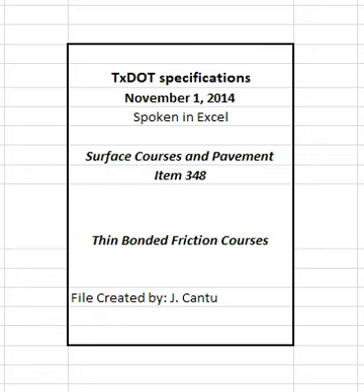Referee tests will be performed only on the sublot in question and only for the particular tests in question. Allow 10 working days from the time the referee laboratory receives the samples for test results to be reported. The department may require the contractor to reimburse the department for referee tests if more than 3 referee tests per project are required and the engineer's test results are closer to the referee test results than the contractor's test results.